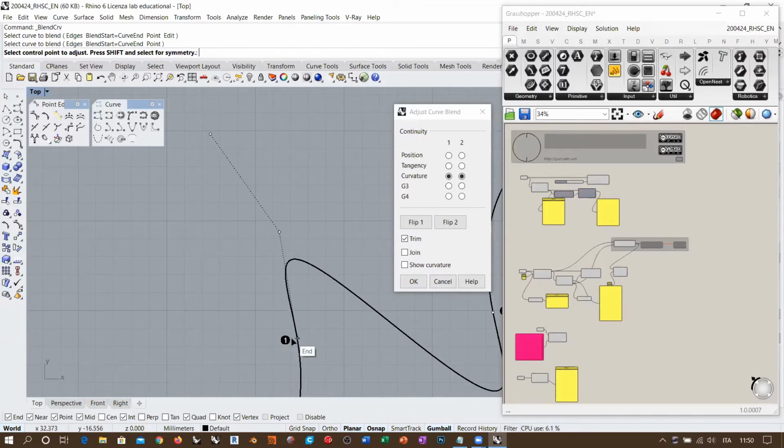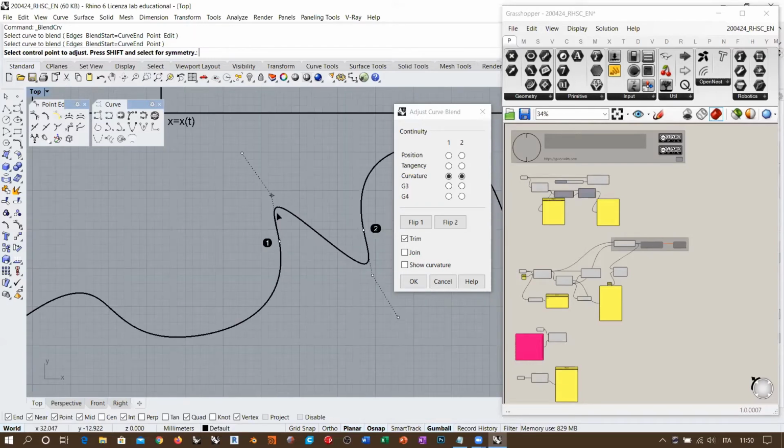These 3 control points are basically symmetrical with respect to the center control point. Okay, they have some angle here. If they are 3 control points, they will create a degree 2 curve. The arc, being part of a circle, is a degree 2 curve. So these 3 control points here are defining exactly the control polygon for an arc. This arc represents the curvature of this first curve in the end point.